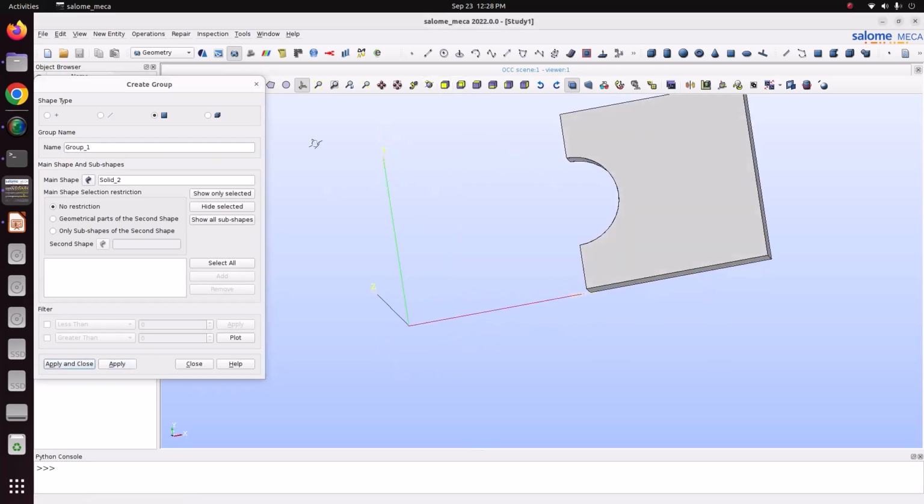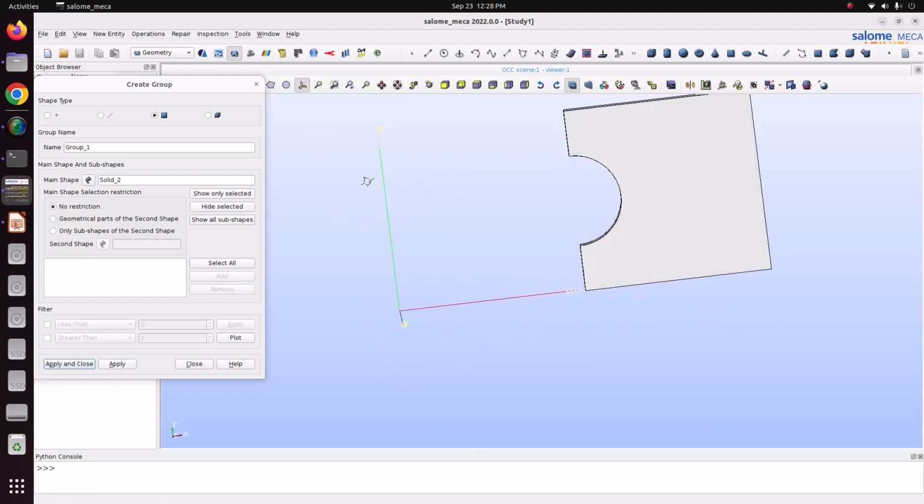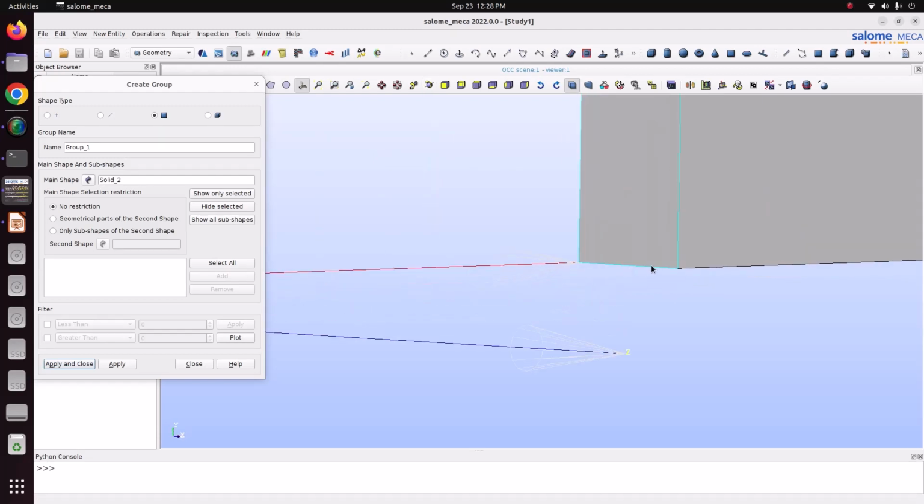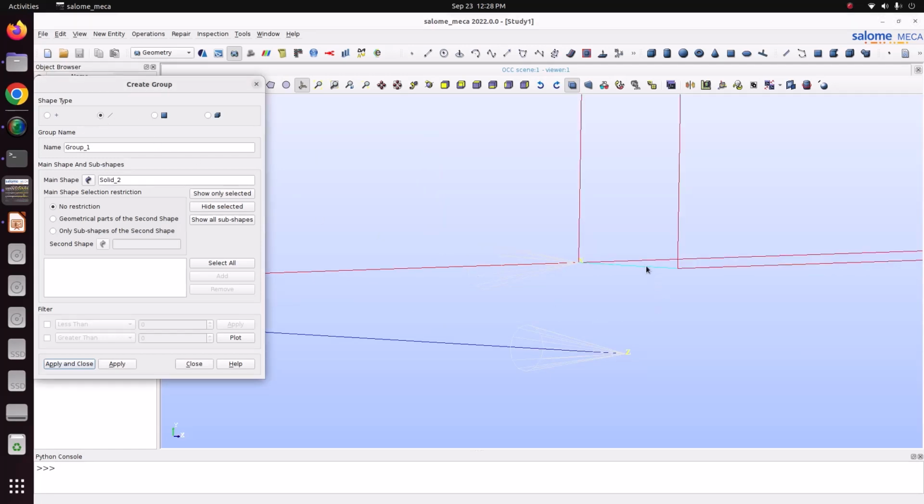Then for the 3D model we need to constrain 3 directions: the x direction, y direction and z direction. So here we have fixed normal to x. One direction we have fixed. Then we'll fix y and z of this particular edge. For that go to line, edge, add. This one you make fix y and z. Then apply it. Now again go to this one.